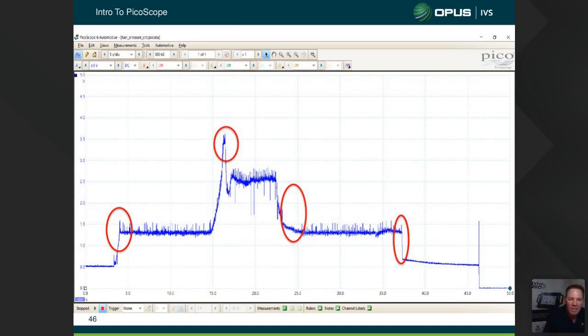We do see some differences when we've got a twin piston pump, like a Denso pump, versus a 3-piston pump, which is like this one is. Our pressure values are a little bit different inside there, but essentially the test is identical. And the 3 points we look at when we do this test. So over here, we've got ignition turned on, but nothing much happening. We can see we're around 0.5 of a volt sitting on that one.